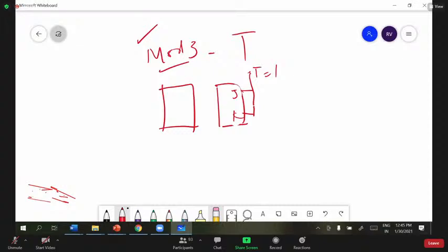the clock signal is given here. Okay. Then clock is connected here. Then these should be connected to logic high. Mod 3, I said it should count from 0 to 2 only. Actually 1 1, it should not count 1 1. That means it should count from 0 to 2. It should not count this 1 1.